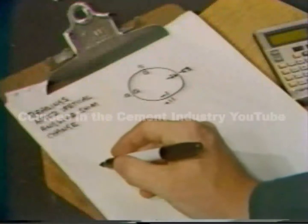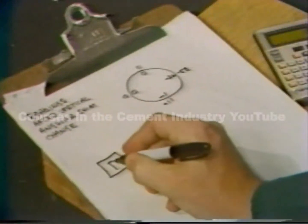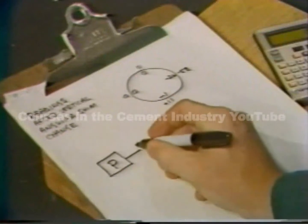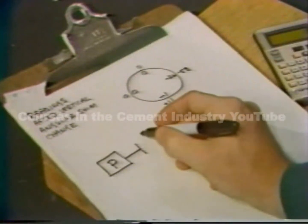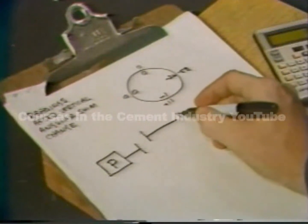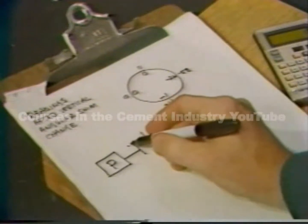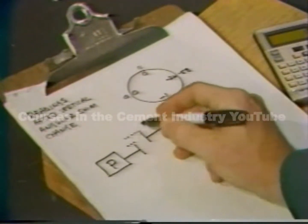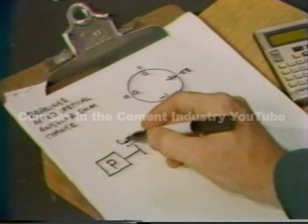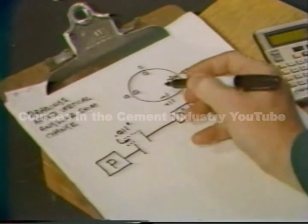This is the data sheet showing the readings taken after the vertical angular alignment correction was made. You'll notice that the vertical angular is now down to a negative 1/1000th, which is well within specifications for this machine. The vertical parallel, on the other hand, shows an 11/1000th offset. Because it's positive, it means that the motor is 11/1000ths of an inch higher than the pump.